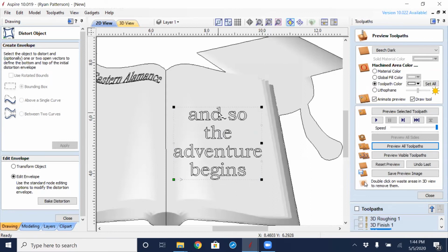I do want to have a node straight up on the bottom and top from both sides. So I'm just going to hover over top of that center and type the letter I for insert, and then I on the bottom. And now at this point, we're going to bump this down a little bit.